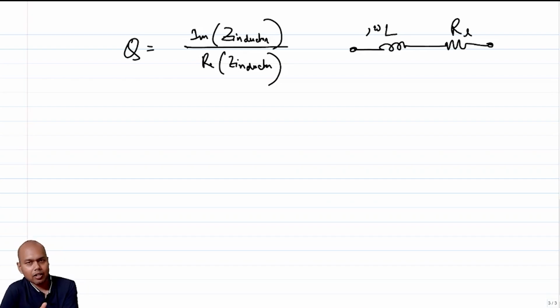It also has a proximity effect, for which I did not give you the formula, but if you simulate it or characterize your losses when you design, you will see that the resistance due to the proximity effect increases faster than that of the skin effect, and so on, right? So even though this simplistic model tells us that if you keep increasing the frequency, your Q factor will increase linearly, that's not true. It will increase and it can saturate, right?